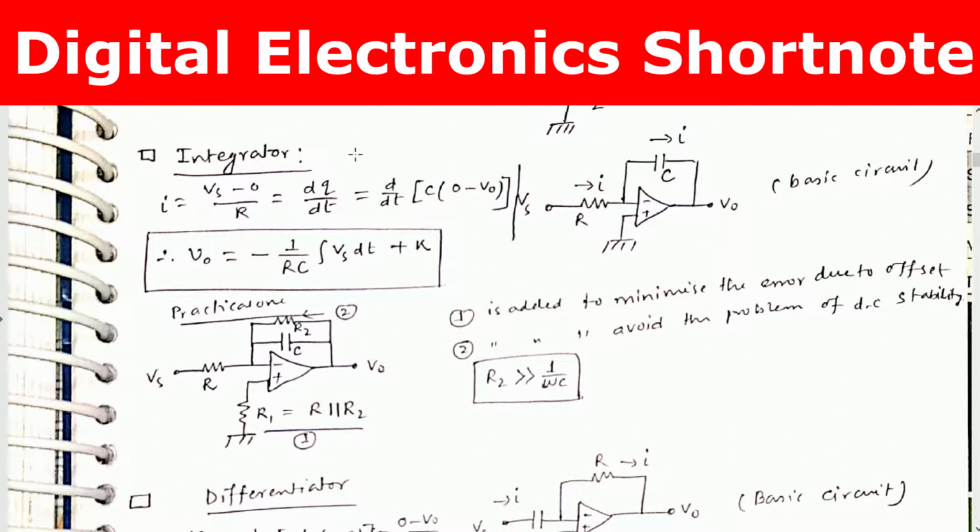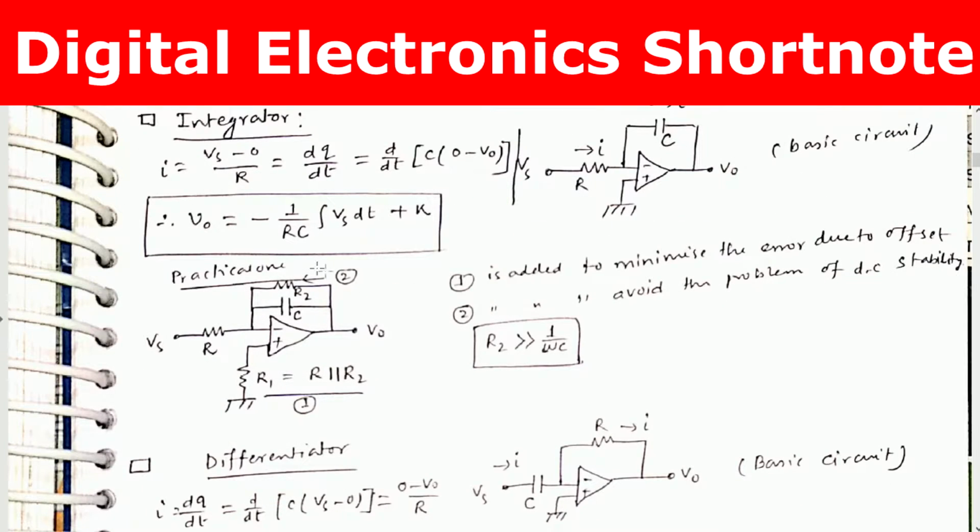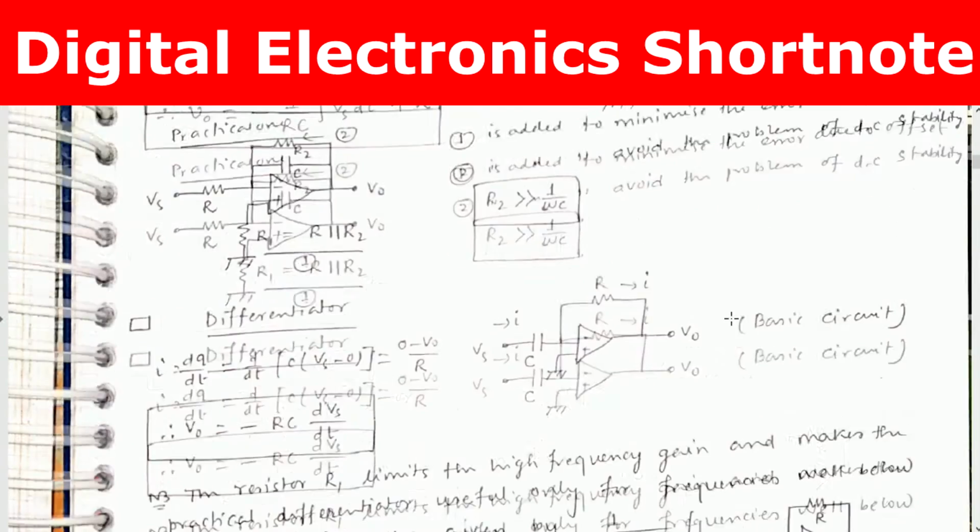So this is the ideal circuit for an integrator, and in the case of a practical one we need to add something. We need to add a parallel resistance R2 and a resistance here at the non-inverting terminal, and the values are decided: R1 should equal R parallel R2, and R2 should be much greater than 1 by omega C. This resistance R1 is added to minimize the error due to offset, and this resistance R2 is added to avoid the problem of DC stability.